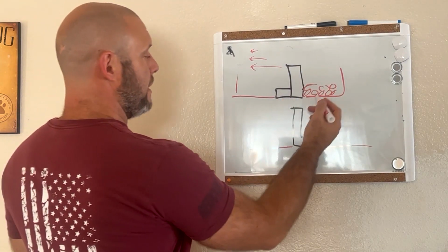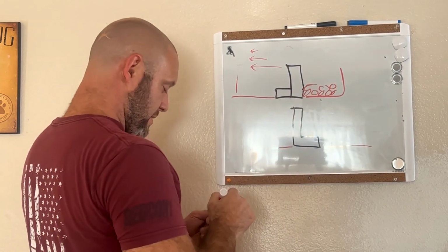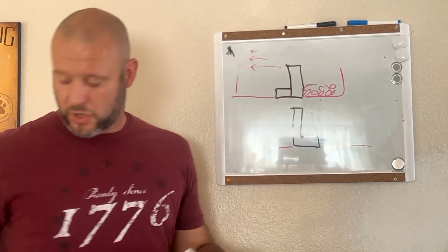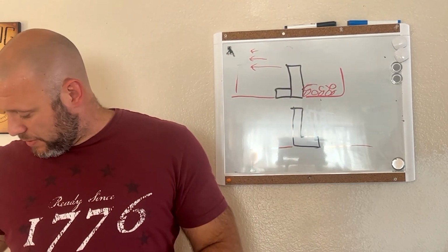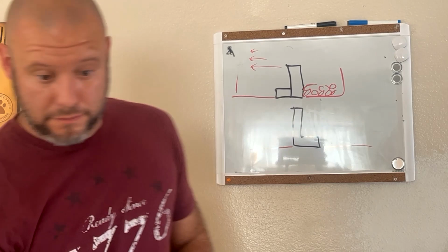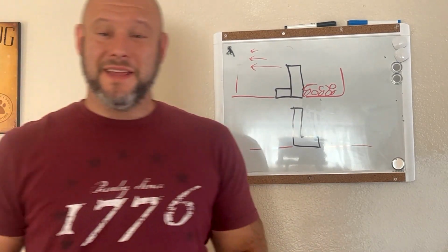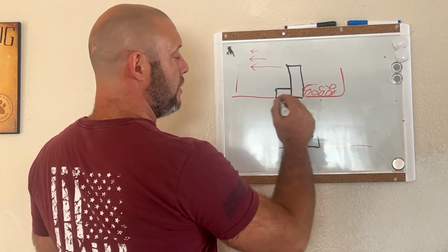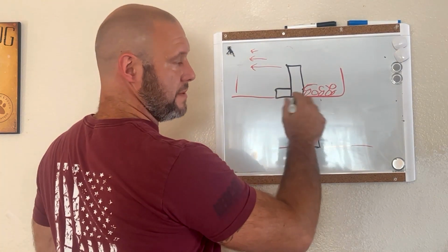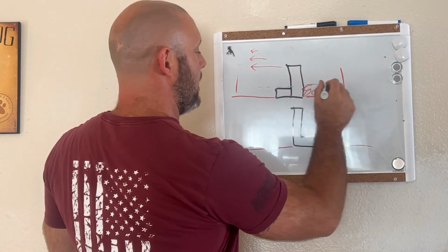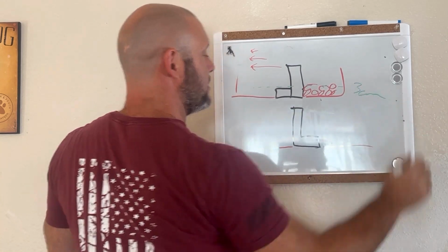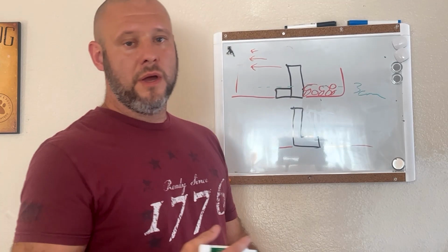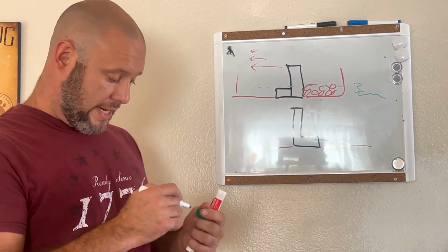And as they fill it up, they get this slide. In this experiment, they were measuring how many centimeters tall they could get the marbles into this guy. When it was just free alone, without the geomaterial or friction mat simulation, what they eventually got was 3 centimeters of height of marbles before they experienced a sliding failure of this model retaining wall.